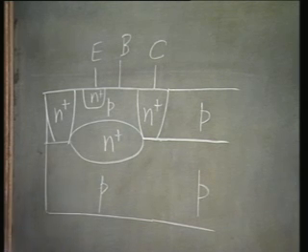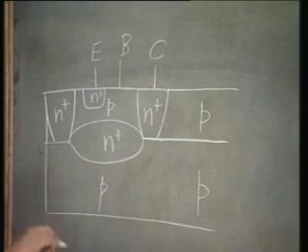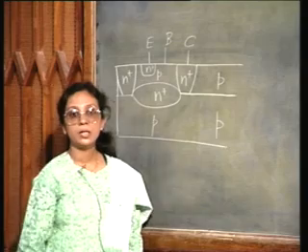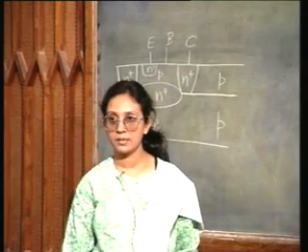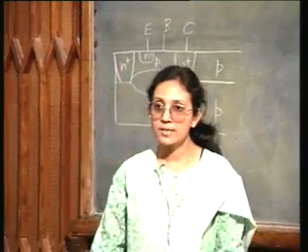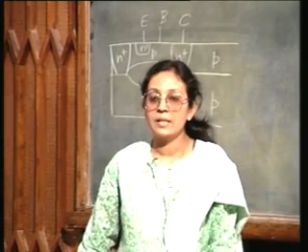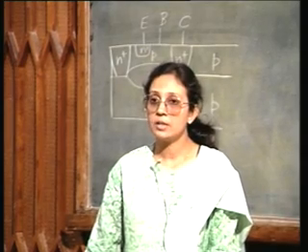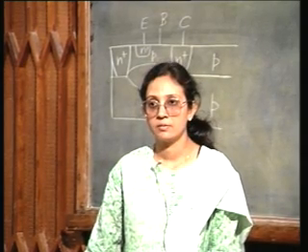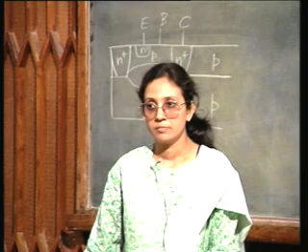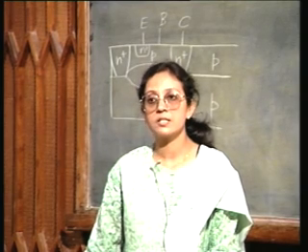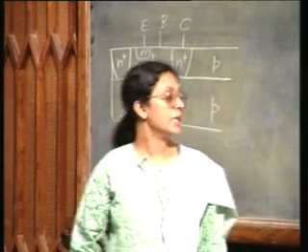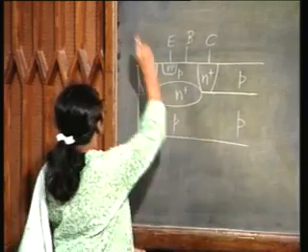That is, each transistor is surrounded by N plus region, by this N plus P. Now, collector is N plus. I have throughout N plus collector, and this collector substrate junction is isolating the two adjacent devices. The reverse biased collector substrate junction is creating the isolation. So, you see, this is called collector diffusion isolation.